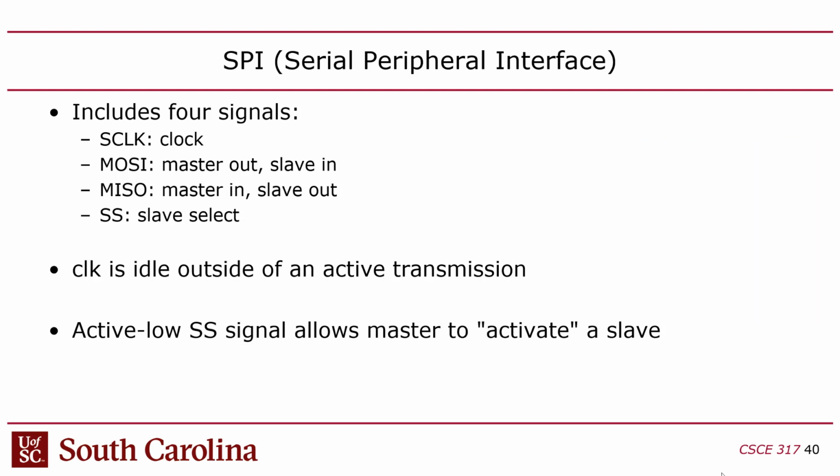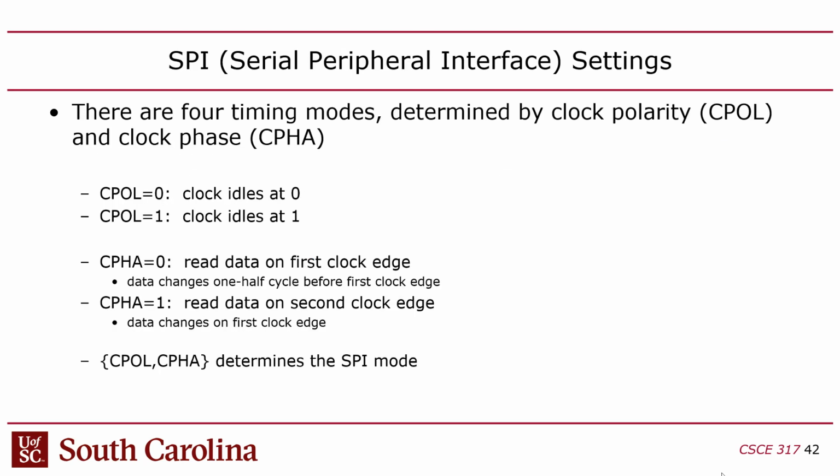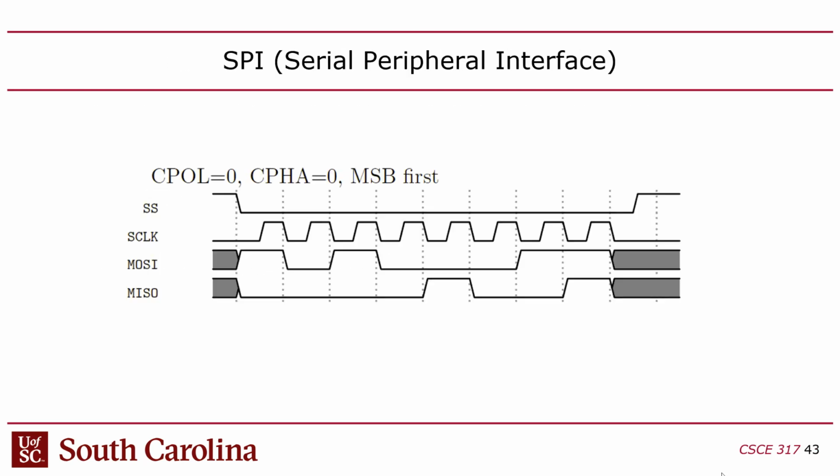And so in order to understand how this works, you have to be comfortable with reading timing diagrams. You might have seen some of these already in 212 or 211. A timing diagram is a plot where the horizontal axis represents time, the flow of time. So from left to right, you've got time advancing. And then the signals are plotted. If you have parallel signals, in this case we have 4 parallel signals, they're just shown on top of one another because they're all operating in parallel, right?